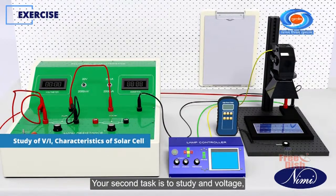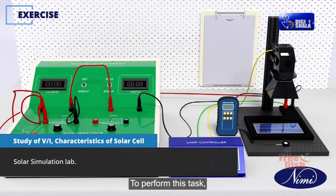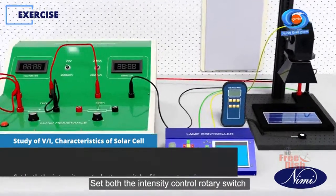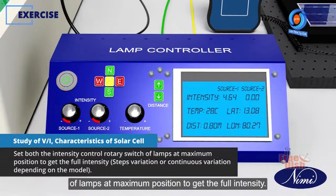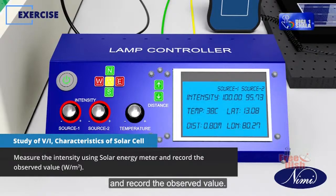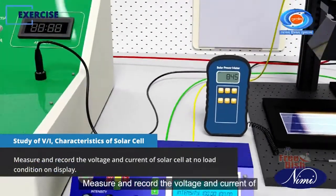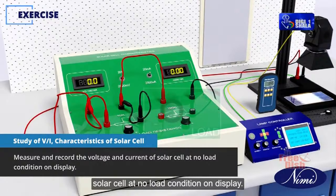Your second task is to study the voltage, current characteristics of a solar cell. To perform this task, you need a solar simulation lab. Connect the solar simulator equipment to the mains power supply and switch on. Set both the intensity control rotary switches of the lamps at maximum position to get the full intensity. Measure the intensity using the solar energy meter and record the observed value. Set the variable resistor load at high to simulate no load condition. Measure and record the voltage and current of the solar cell at no load condition on the display.